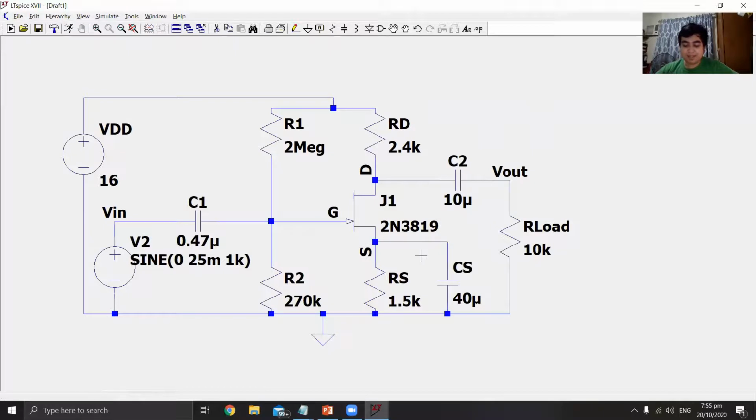As for the disadvantages, FETs have a drawback of smaller gain bandwidth product compared to BJT. Faster switching times can be achieved in BJT compared to FET, and performance of FET deteriorates as frequency increases due to the feedback by internal capacitances.